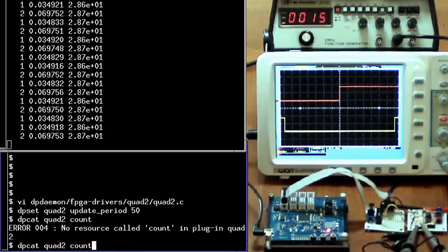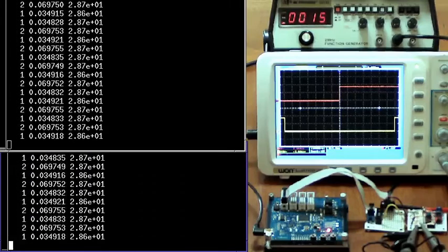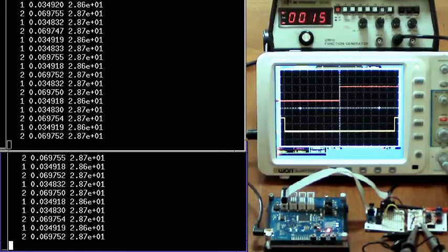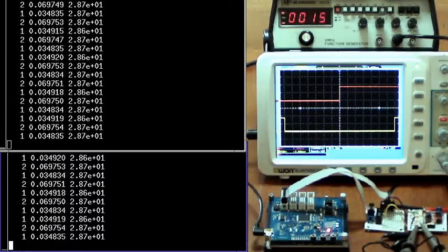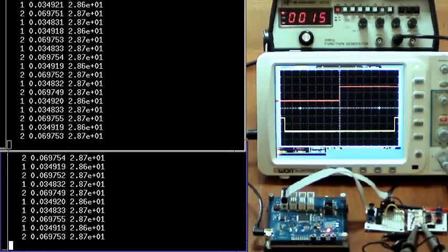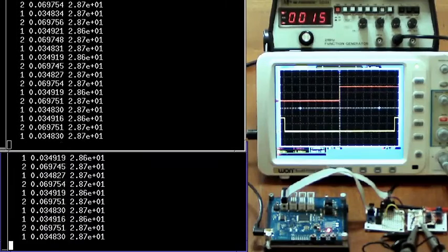The idea of having multiple subscribers makes it easy so that if you want to have one process or thread do motor speed control, you can have an entirely separate process or thread do navigation based on these quadrature readings.